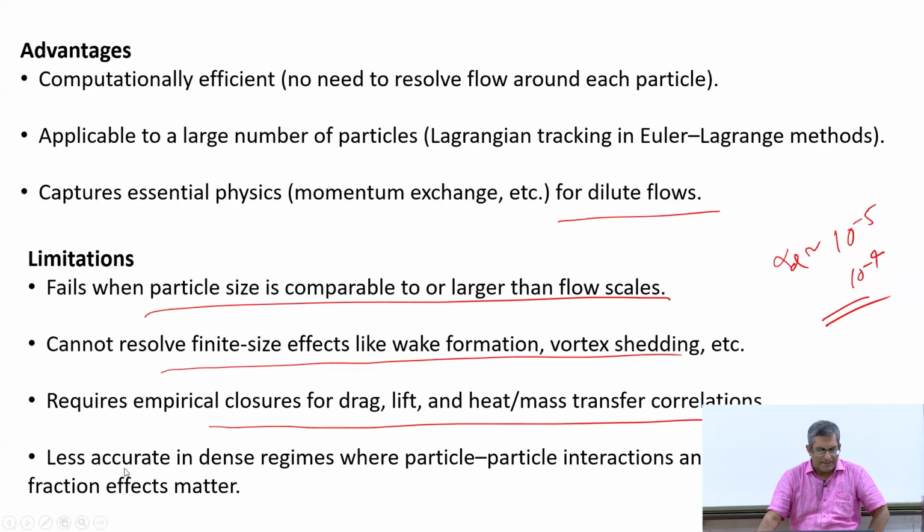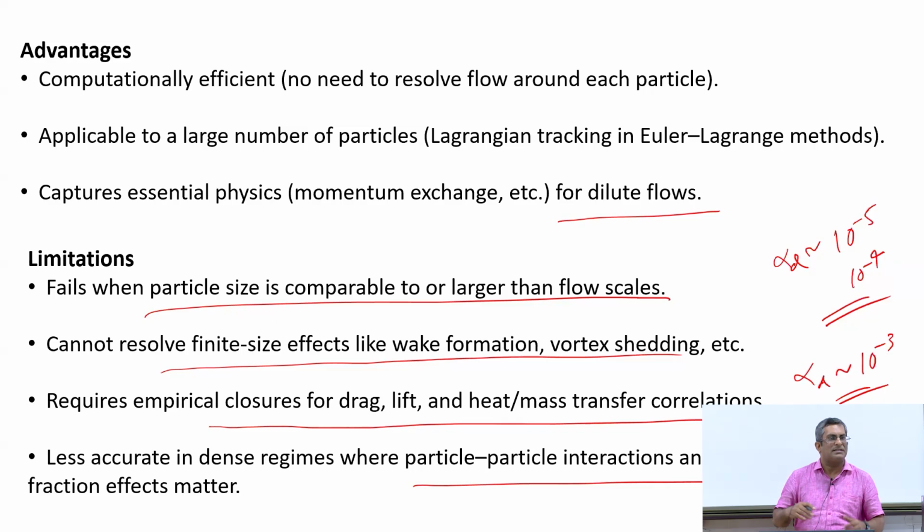And as I said, it is less accurate in dense regions where particle-particle interactions come into the picture. For example, fluidized beds where you have really dense loading, where the volume fraction is of the order of 10 to the power of -3. In such cases, Lagrangian particle tracking using point particle assumptions should not be used.